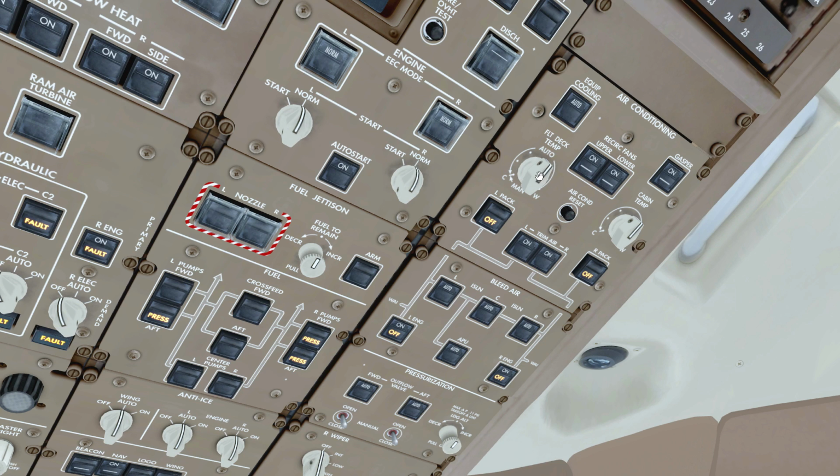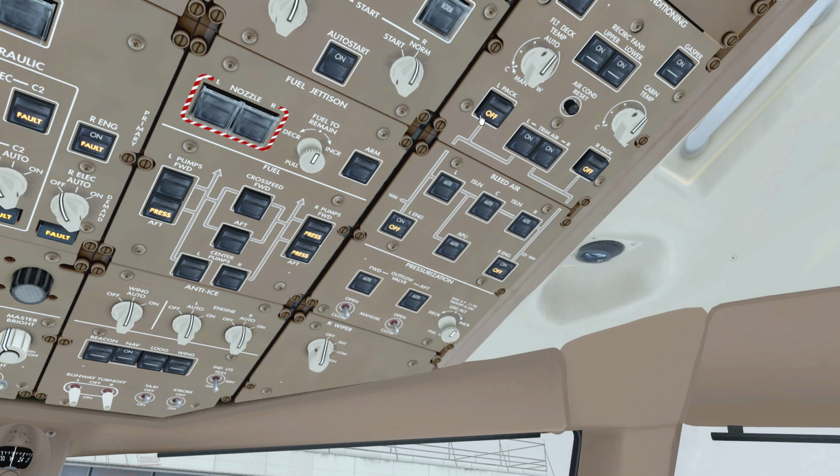Flight deck temperature, just make sure that these knobs are in the middle, so that the temperature is auto regulated for the flight deck and the cabin. But if needed, you can adjust it and make it warmer yourself. Then we have the PAX. Now the APU is running, so of course we can let the APU supply some air, so you will hear some more airflow once we turn the PAX on right now. There we go, so now the aircraft is being air conditioned.